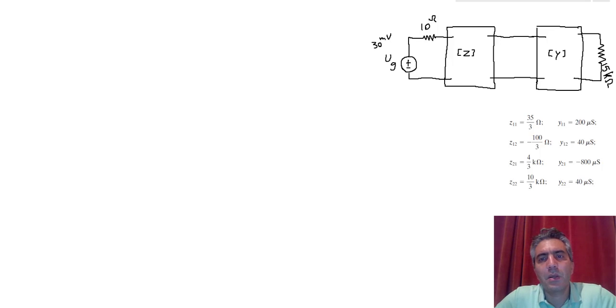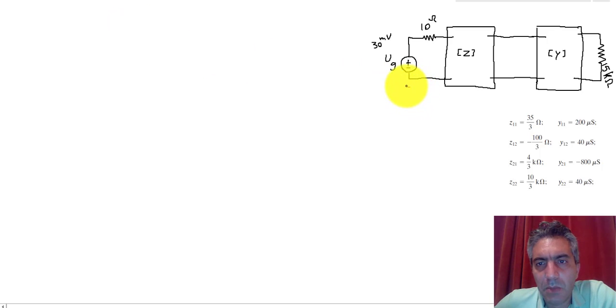Hello everyone. In this video we're going to practice analyzing circuits that include two-port subsystems. In this specific example we have two subsystems, for one of which we have the Z parameters and for the other one we have the Y parameters. The process is exactly the same. We're going to start by identifying the nodes, and then after which we're going to name them.